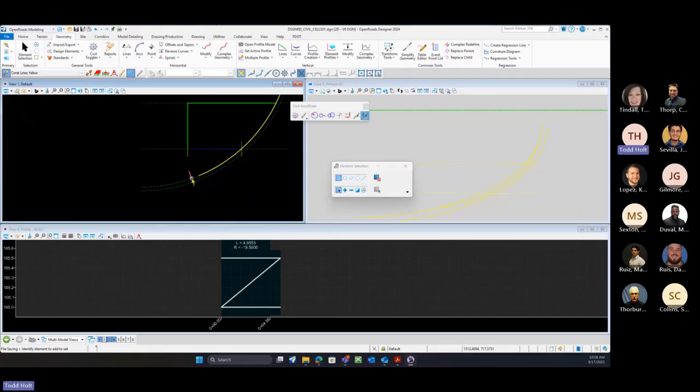All right, we can do the same thing on this side. Maybe it's a certain distance along this curve back that we're tying there. So we're going to turn back on our civil AccuDraw. I'll hit O. Select my reference. Let's select my reference point.